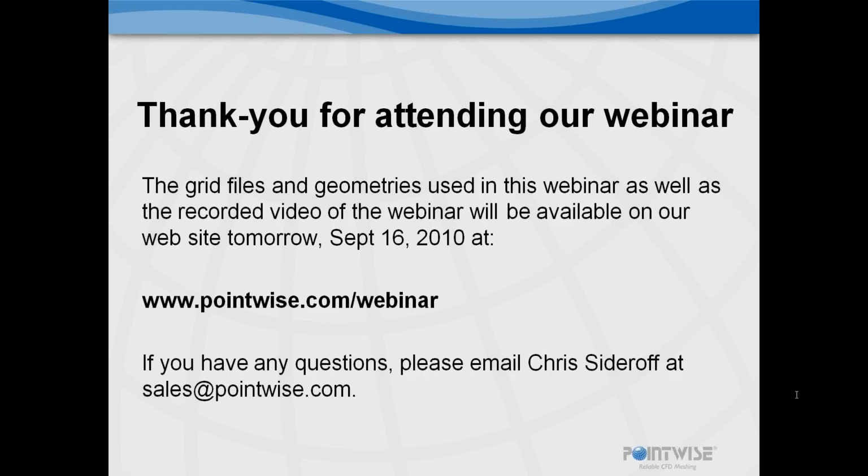Yes, there's a question that says, if your solver can handle an unstructured mesh, what would be the reasons for creating a structured block mesh? In general, a structured block mesh is going to be much more efficient, both computationally in terms of the number of cells and points required to get an equivalent answer to an unstructured mesh. But also, you tend to gain some accuracy simply due to the fact that when you lay out your topology, as Chris has done here, you create many grid lines and faces that are flow aligned, and those are going to minimize discretization errors for a given mesh size. So there are computational benefits to the structured mesh, but there is also an accuracy benefit.